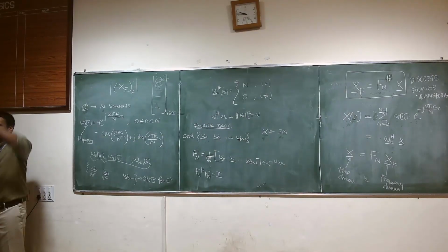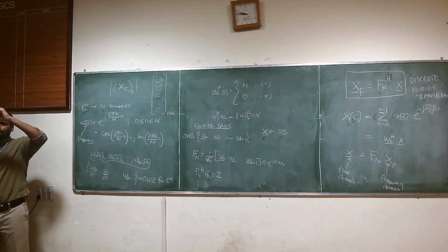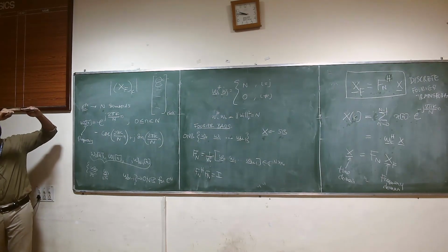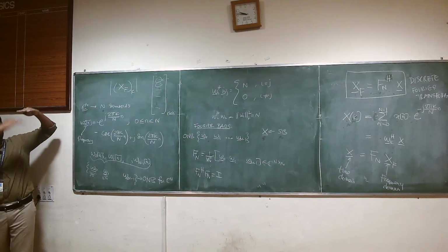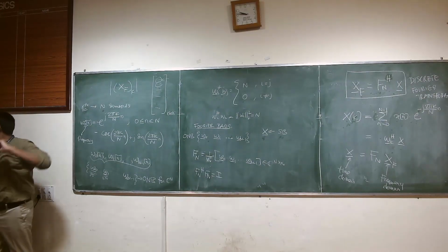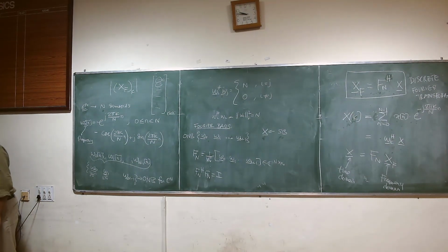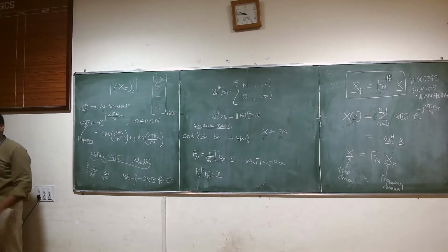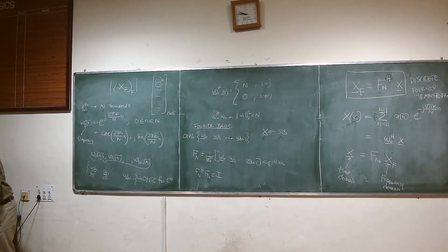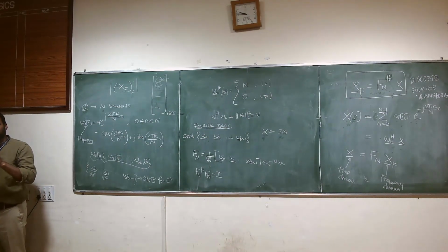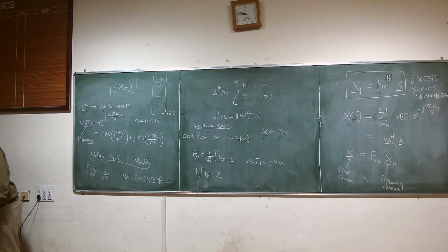So you have a huge value for the signal, and then tiny variations about that huge value, which essentially tells you that the major component is this average value. These tiny components don't appear if you take this large average value into account. So it does make sense that the signal has a large average value. Let's say we remove the average value. What we are more interested in is this rhythmic pattern itself and not the average value of the signal. So I take the signal, I compute the average, and I subtract the average out. That means it has no DC component anymore.